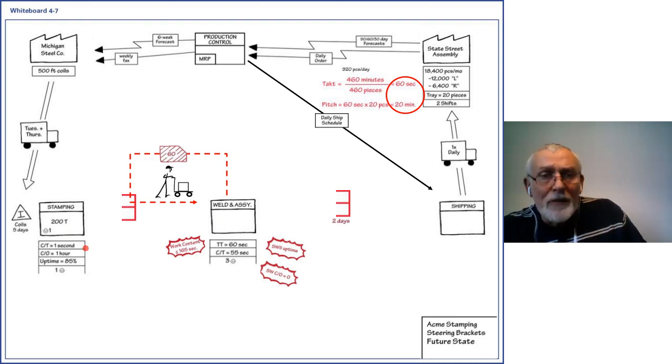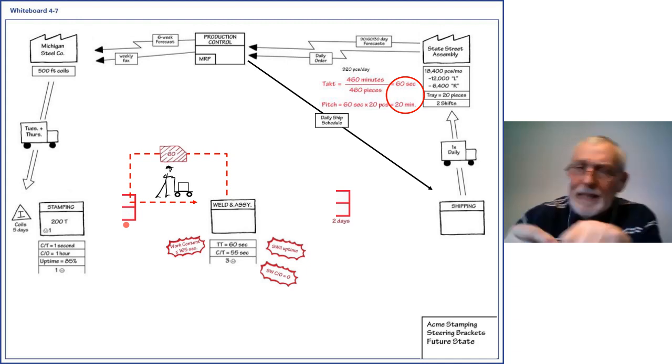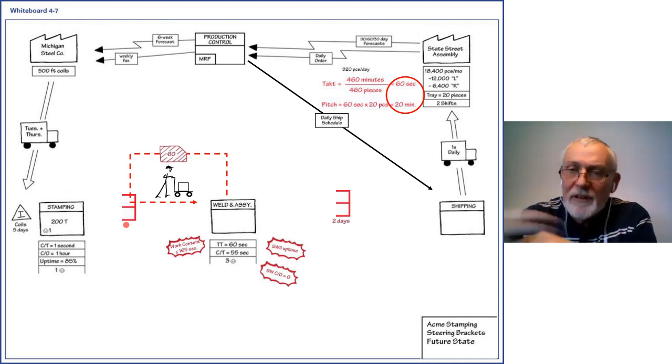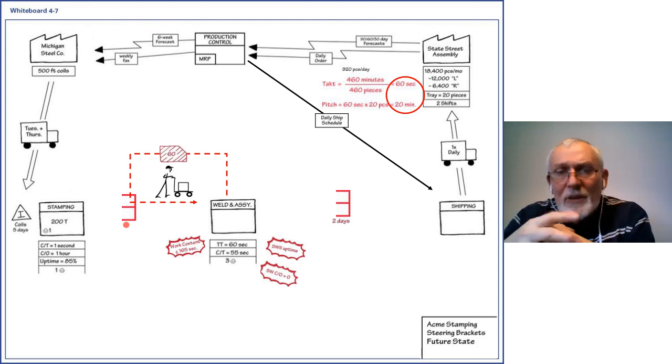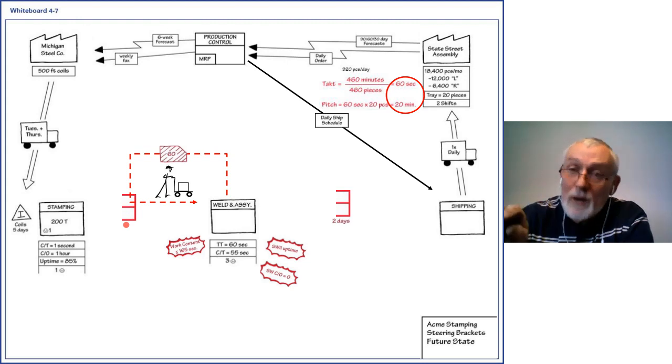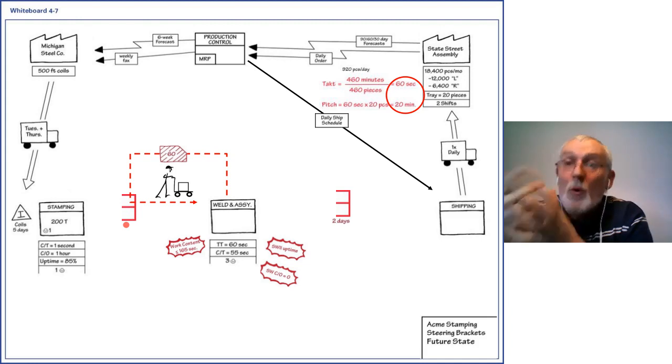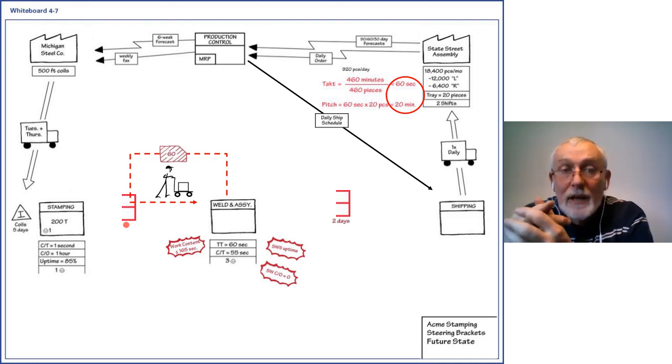Similarly, on the stamping press, we're going to use a slightly different system. This is a signal Kanban rather than a production and withdrawal Kanban, and again, we'll cover that in other lectures. But essentially how this works is as the stampings are used up and taken out of the supermarket, the cards effectively are gathered together, and when they reach a certain batch quantity, then they're fed back into the stamp, and that will cycle through its quota, if you like, of parts for this line.